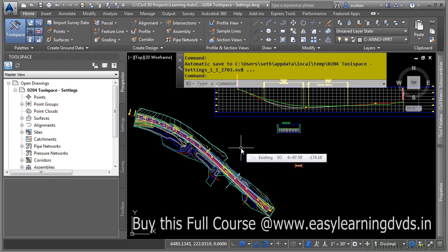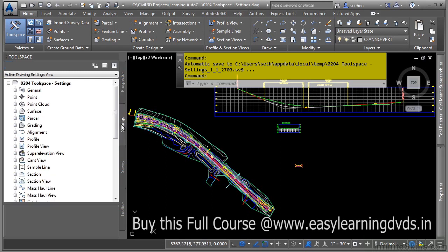within your organization. The way Civil 3D works is that styles and settings are stored in a drawing template, and this makes it very easy for you to maintain your CAD standards or use Civil 3D with another client's standards. There are two types of styles in the world of Civil 3D. We have object styles and label styles. So let's navigate to the Settings tab. And let's go ahead and just look at an example object style.